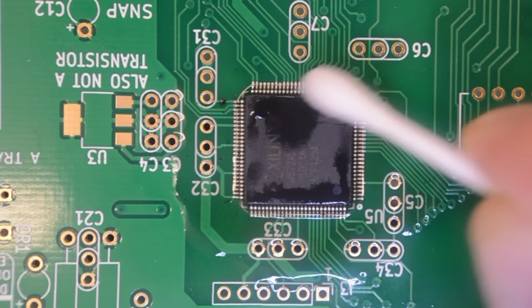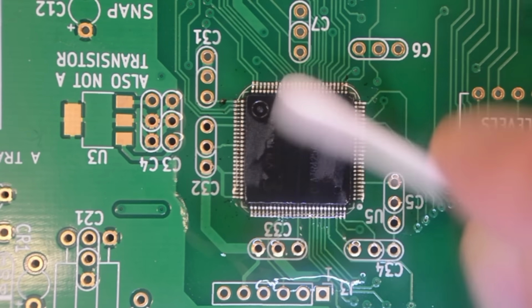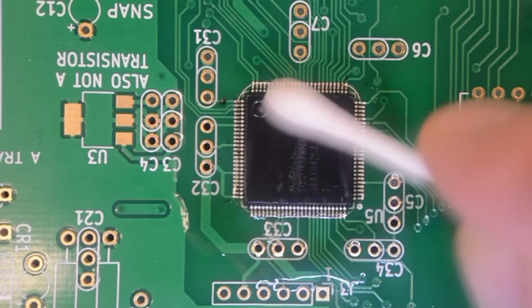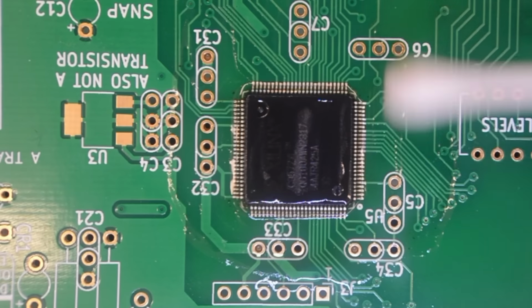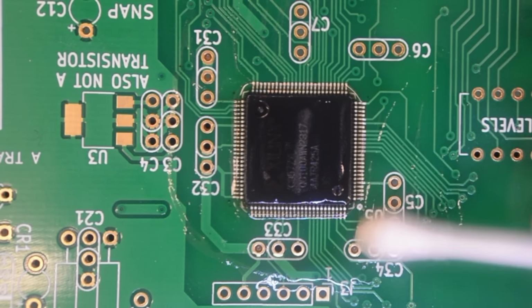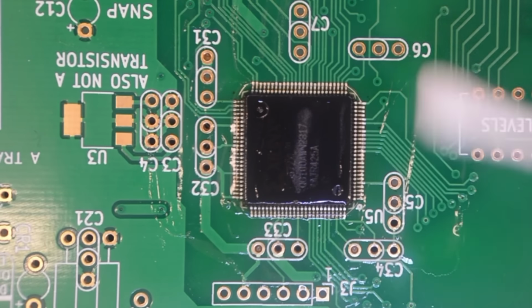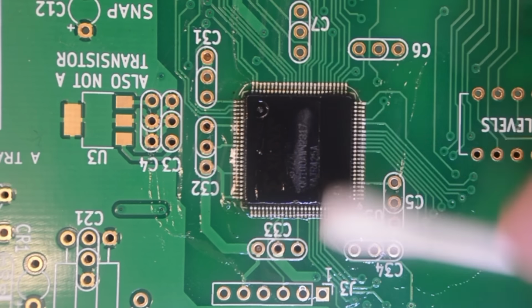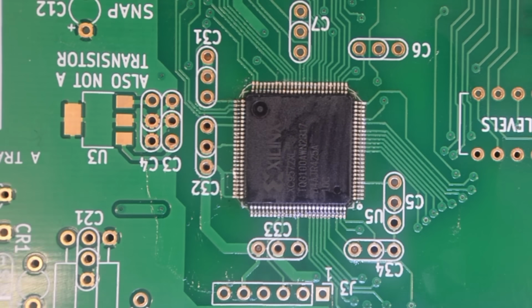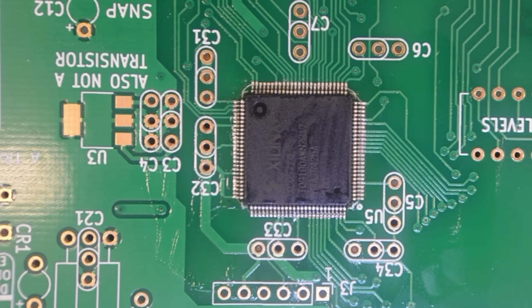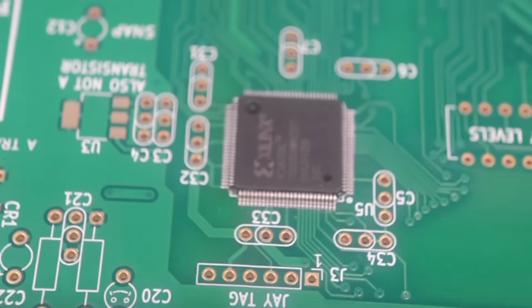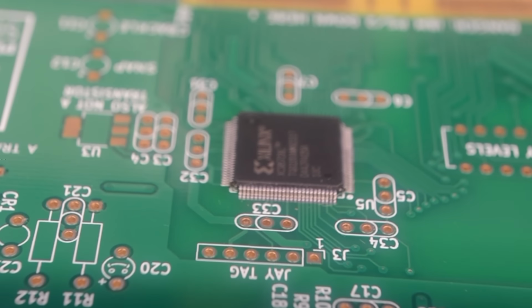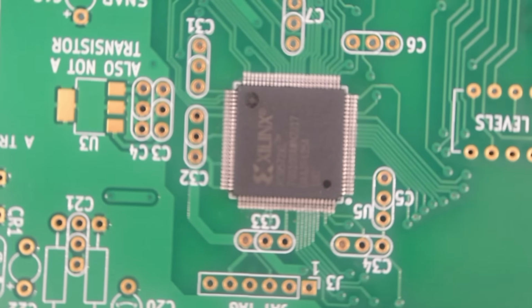Okay, the next step is to dip a Q-tip in IPA and clean up the flux. I usually don't use a brush, because then you have to clean the stupid brush. Okay, before I clean some more, I'm gonna grab my loupe and do an inspection. Okay, board cleaned up, and I did an inspection. And I'd say this is good enough for me.